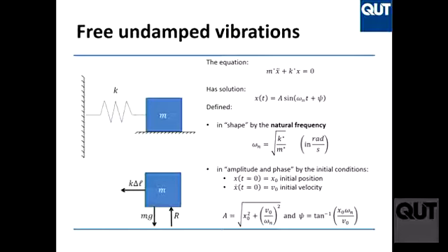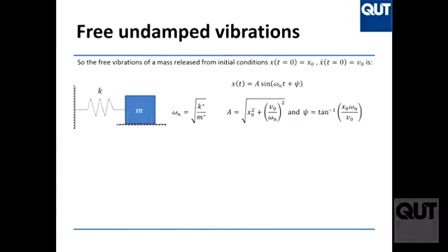if I force this system with, say, 1 hit per second, it will vibrate at 1 hit per second. The system will always vibrate at the same frequency as the force you're putting in, if you're talking about forced vibration. But in this case, there's no force, so the free system is free to vibrate at whatever frequency it wants. And if that's the case, the system will vibrate at its natural frequency, and the natural frequency depends only on the property of the system. Okay? Have I at least partly answered it? Okay.